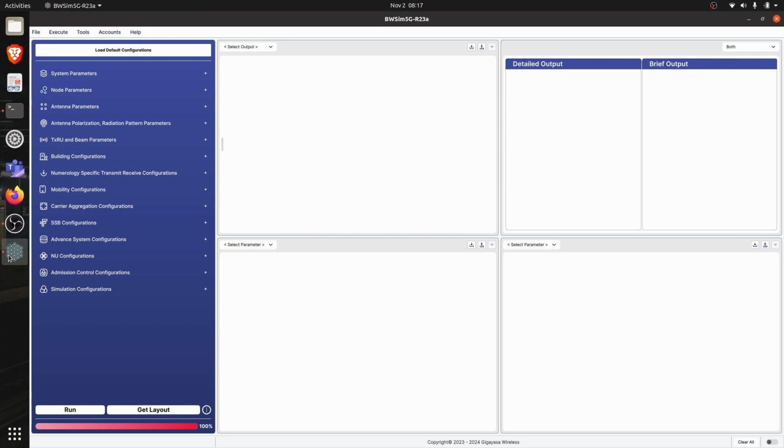Similarly, for other applications like CSI compression and feedback, rank and condition number analysis, and beam learning, we require the presence of a LOS link. Thereby, we need a probability model to determine the presence of a LOS link between the transmitter and receiver. This is where 3GPP comes into the picture, where it has defined a LOS probability model for each terrain. Now, in this experiment, we are going to use those models to check what relationship this probability of LOS has with other parameters. First, we are going to change the terrains and observe the probability model.